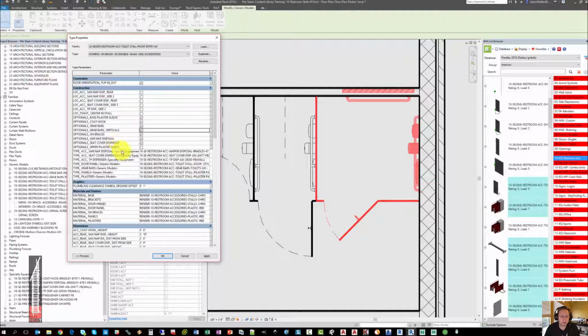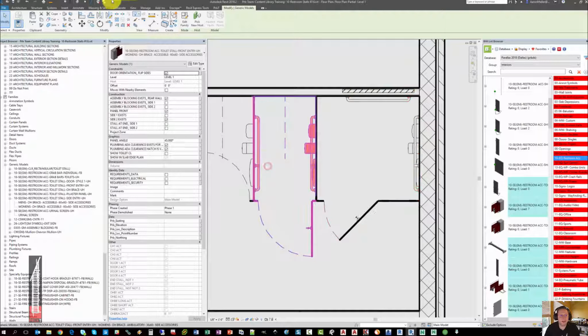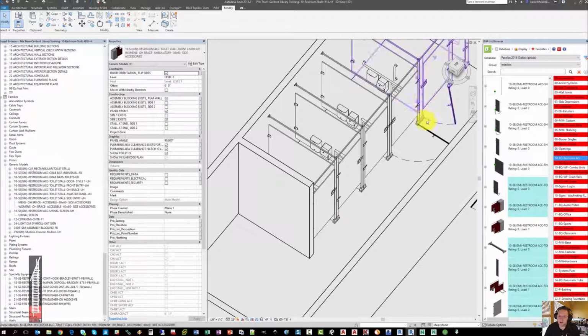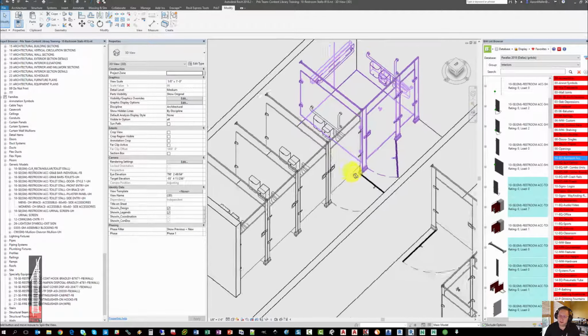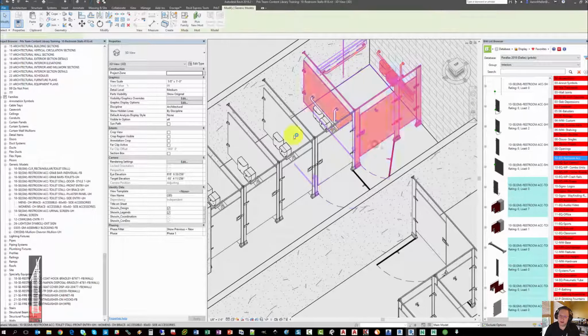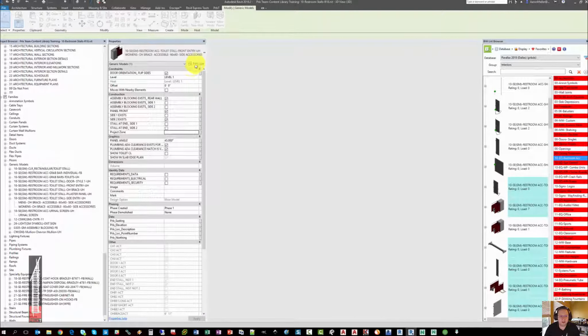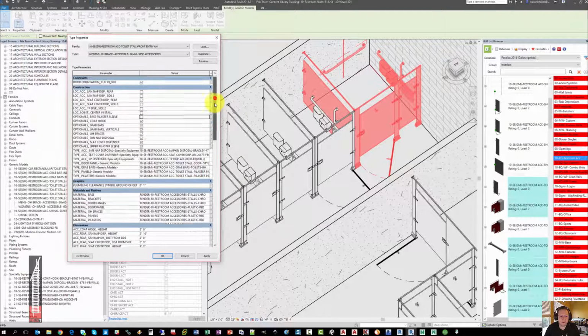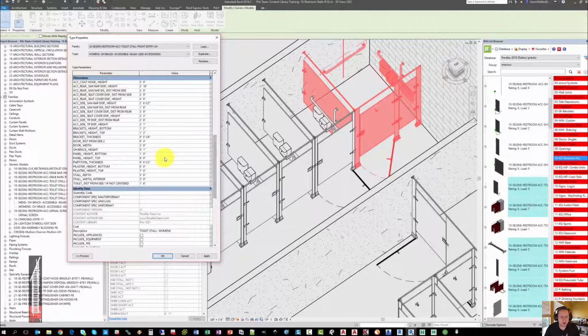And then there are what we call Pilaster Sleeves. Those are best seen in 3D. And essentially, on the overhead brace stall, you'll notice that there are Pilaster sleeves at the bottom. If you wanted to simulate a ceiling hung device, then you could get rid of the overhead braces, turn on the upper Pilaster sleeves, turn off the base Pilaster sleeves, and then it's a simple matter of changing the dimensions to simulate a ceiling hung device.